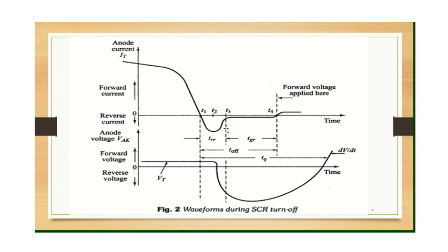So what is happening there? If you observe from T1, after it crosses zero, the anode current reverses its direction. That means it starts flowing in the negative direction. Say at instant T2, you have applied the reverse anode voltage. Then the reverse recovery current continues to flow in the reverse direction, or continues to decrease, when you are applying the reverse voltage.